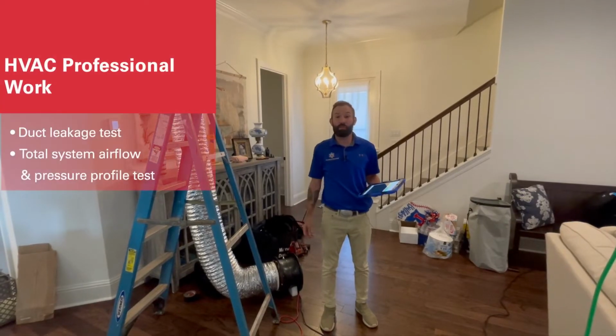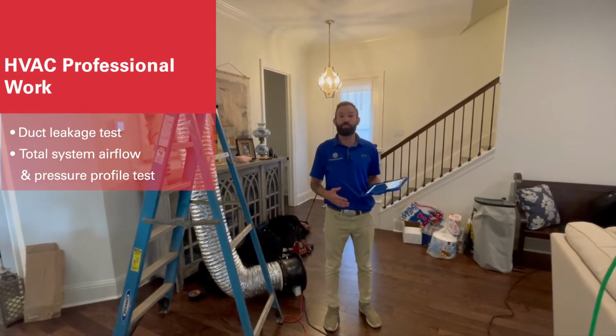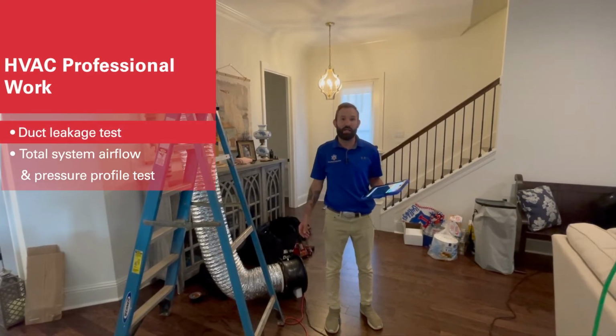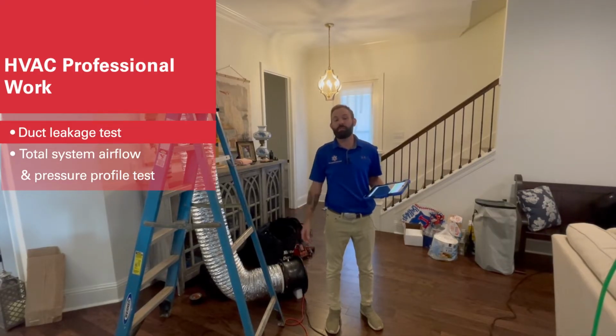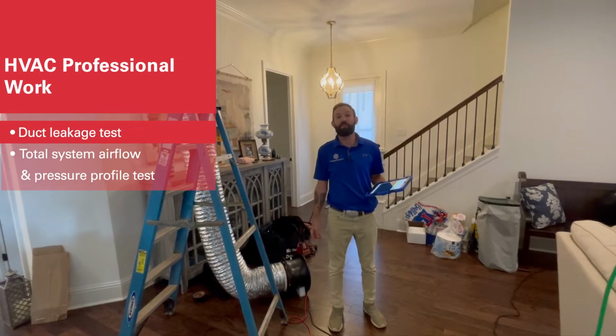As the HVAC professional, my first move in an application or a house that is typically negative, which is what we have seen with the indicators given to us by our colleague on site, our first step should always be to test the duct system for total leakage. So at this time, we're going to go ahead and run a duct blast test for total duct leakage.